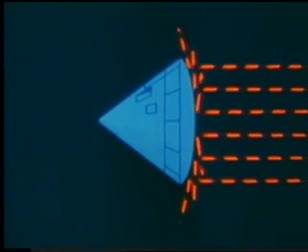The aerodynamic characteristics of the entry vehicle or command module play a decisive role in the Apollo atmospheric entry phase, especially since even after the corridor is achieved, future errors could result in disaster. We will look at this later. Now let's see how this lift is generated. The Apollo command module is basically conical in shape. It will enter the atmosphere blunt end forward. As it does so, it will strike molecules of air.